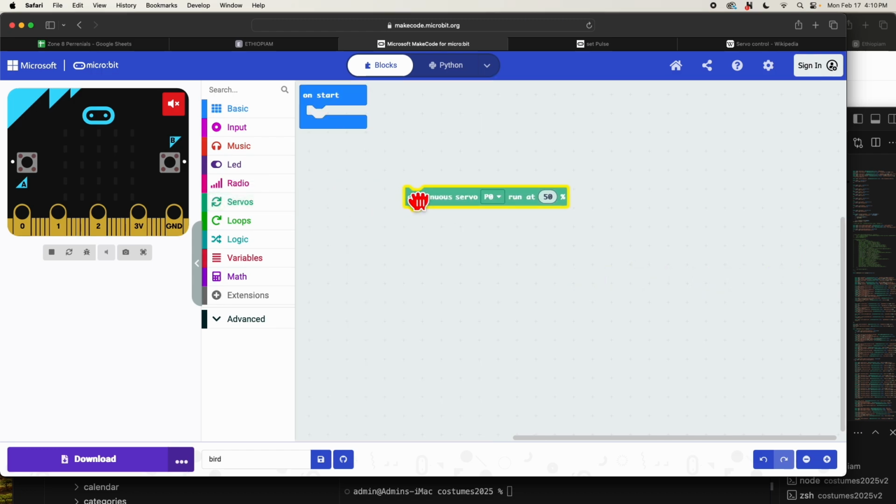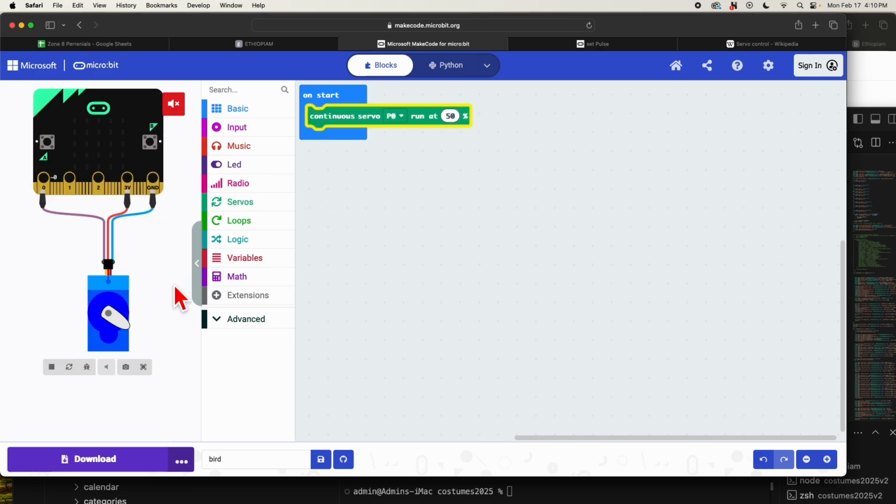Let's drag that onto our surface and let's put it right inside the C block. And you'll notice that in just a few seconds, servo motor will be on screen. And you can see it is connected to port 0. And this is also port 0. We have 3 ports that are available for servos: port 0, port 1, and port 2. So let's leave this at port 0, and let's change this number to 100%. You can either use the slider or you can type that number in 100.